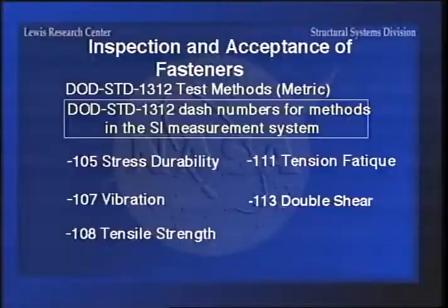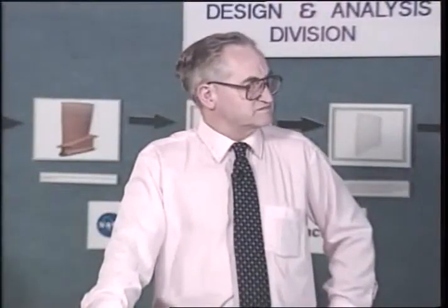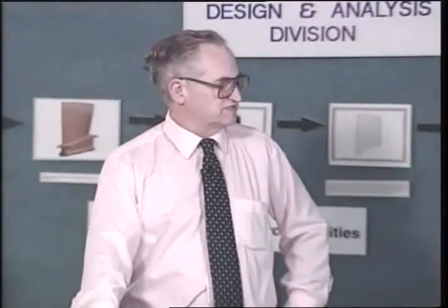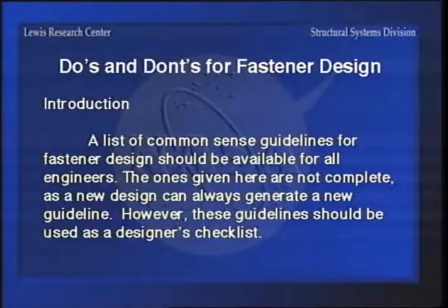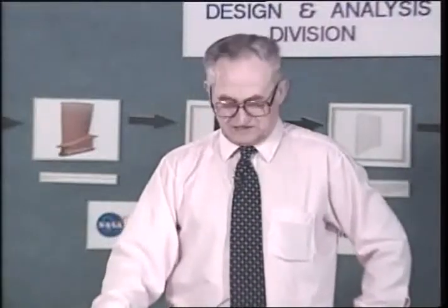Now we go into the do's and don'ts of fastener designs, and I've kind of come up with a set of guidelines here, just common sense type guidelines for you to use, and it's not a complete list because you can always come up with an addition for a list. But these at least could be used as a designer's checklist. And one of the things that's a pet peeve of mine is I feel that enough information should be given on a drawing to fully define the fasteners you want.